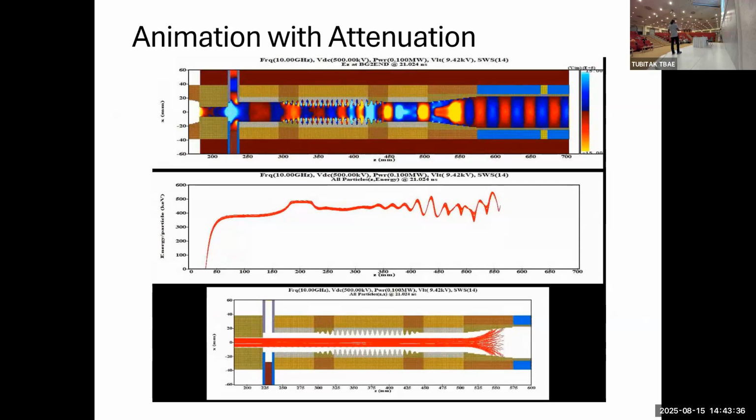It's a nice one. So now the problem is always for these devices is here. Here we are using a mathematical function for the magnetic field, how to taper the electrons, because we are extracting here. Remember, for low power traveling wave tube, you inject the signal from the side and you remove it from the side or extract it from the side. For high power, you can't do that because of the breakdown issue. So you have to generate or radiate from the aperture here.